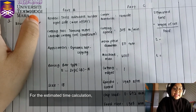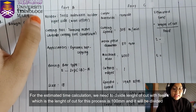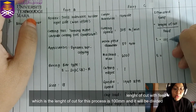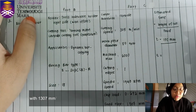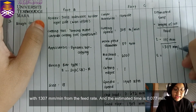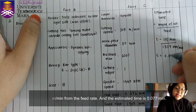For the estimated time calculation, we need to divide the length of cut by the feed. The length of cut for this process is 100 mm, and it will be divided by 1307 mm per minute from the feed rate, and the estimated time is 0.077 minute.